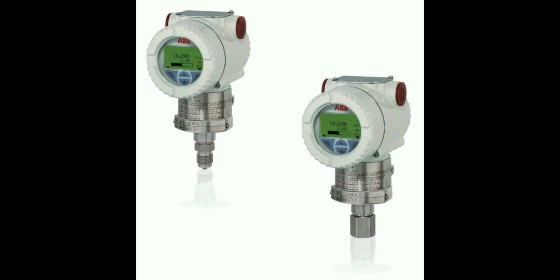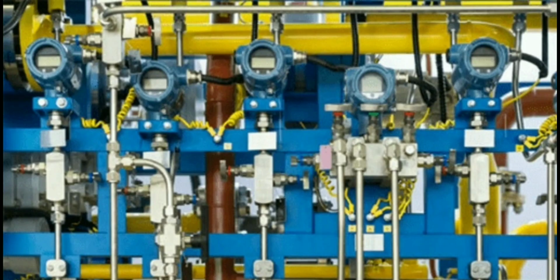Let's look at the advantages of an absolute pressure transmitter. It provides an absolute pressure reading, not influenced by changes in atmospheric pressure. This is essential in applications where variation in ambient pressure needs to be eliminated. It's ideal for applications at different altitudes, as it measures pressure relative to a vacuum. It eliminates the need for altitude adjustments.